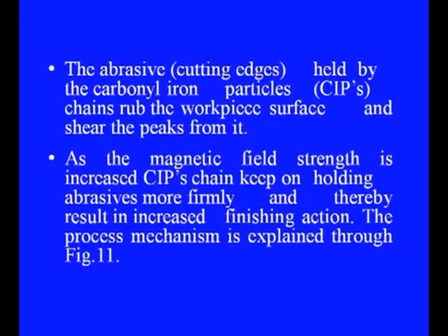In this process, rheological behavior of the fluid changes from nearly Newtonian to Bingham plastic and vice versa upon entry and exit of the finishing zone respectively. This process was first reported by the researchers at IIT Kanpur named Jha and Jain in the year 2004. The abrasive cutting edges are held by the carbonyl iron particles, which form chains and disrupt the workpiece surface and shear the peaks from the workpiece surface. As the magnetic field strength is increased, carbonyl iron particle chains keep on holding the abrasives more firmly, and thereby result in increased finishing action.